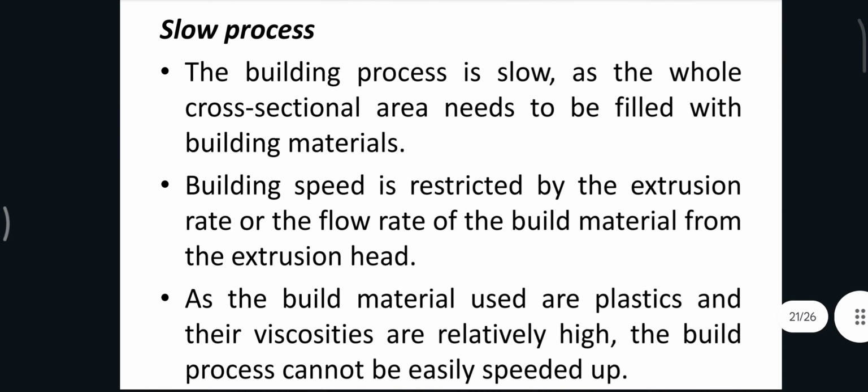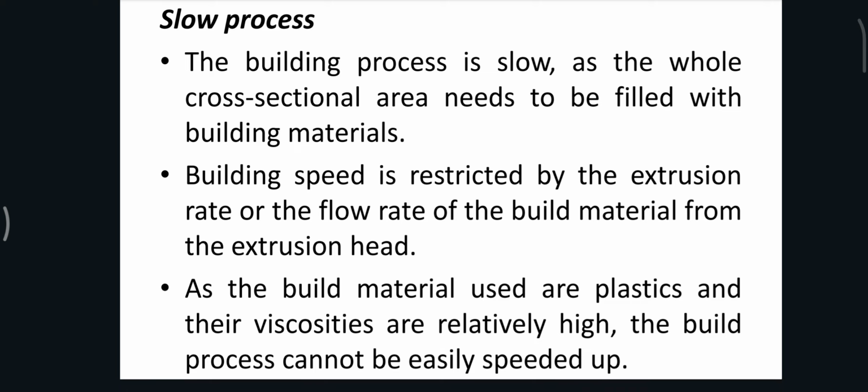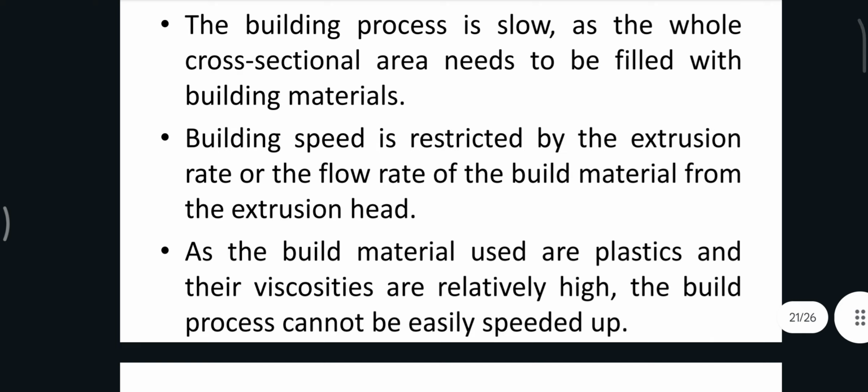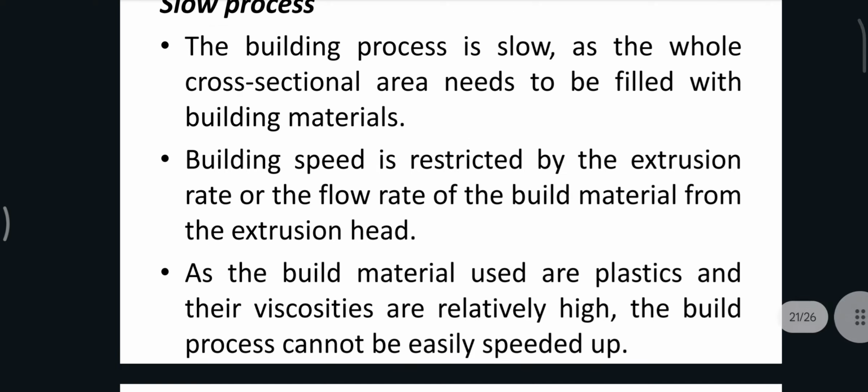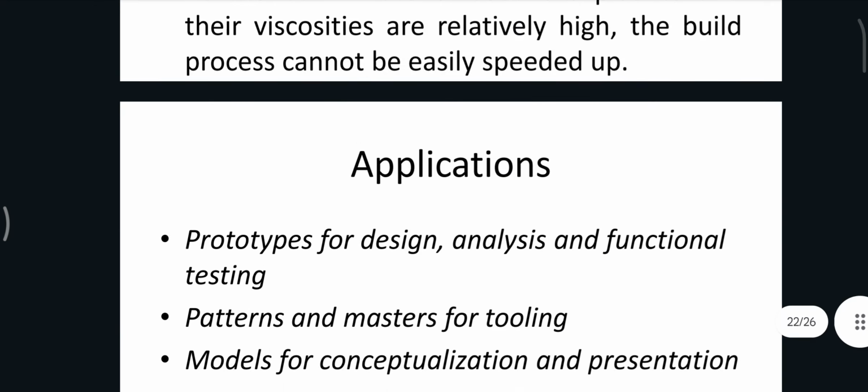Slow process. The building process is slow as the whole cross-sectional area needs to be filled with the build material. Building speed is restricted by the extrusion rate, or the flow rate of the build material from the extrusion head. As the build materials used are plastics and their viscosities are relatively high, the build process cannot be easily sped up.